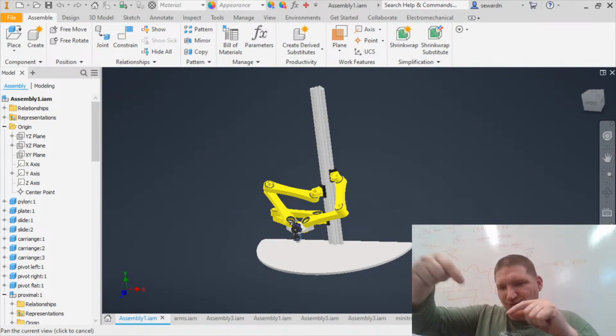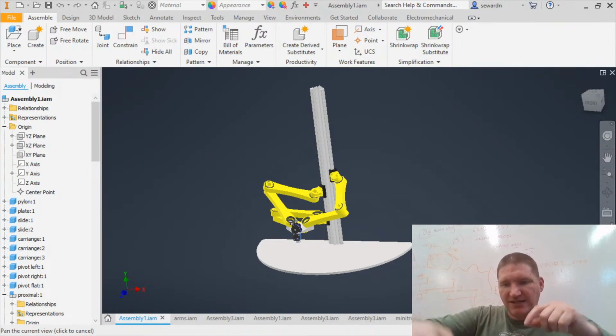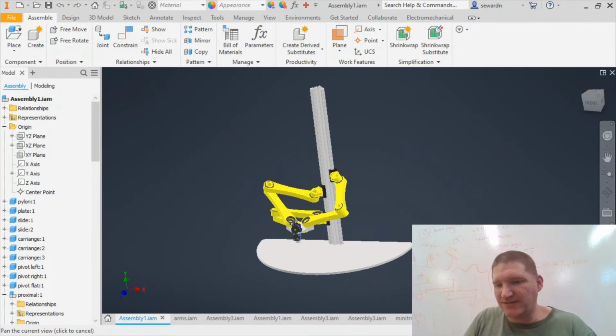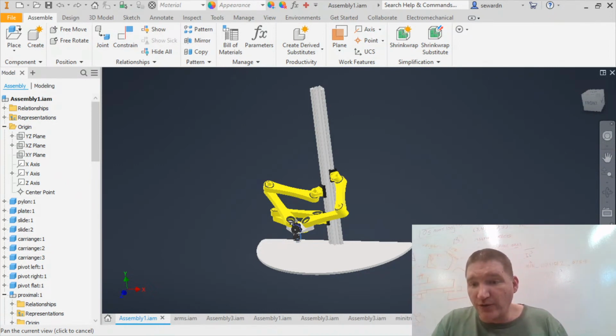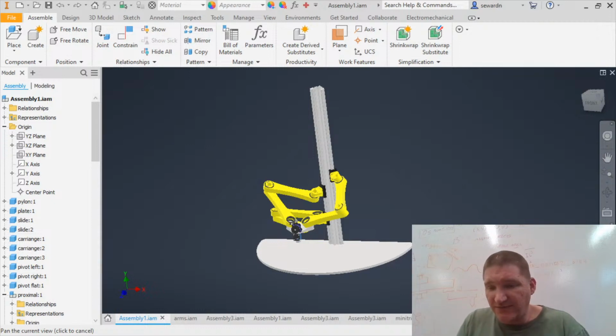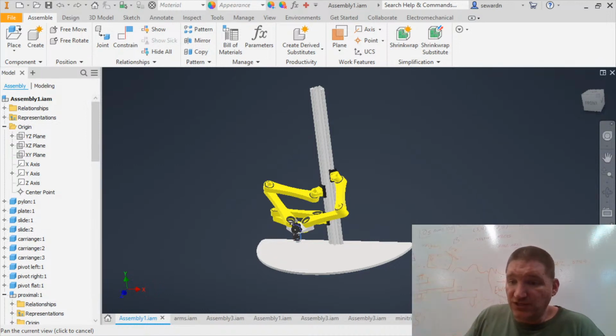Yeah, so it'll shoot a modulated IR beam down at the bed and then pick it up at a different angle, and it'll move down until it finds the strongest signal. Anyways, as long as you don't have a glass bed, it'll work great. You do not want to use stall guard with a lead screw. You could if it was a high enough lead screw and you turn the current down. So yeah, that's another thing: whenever I try to stall it and run it into an edge somewhere, you just got to turn the current down enough so you could skip steps and actually get it to stall.